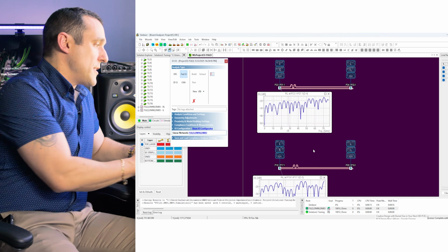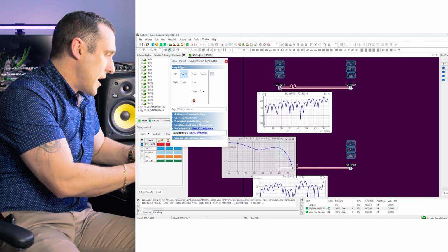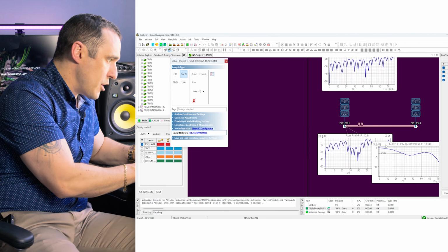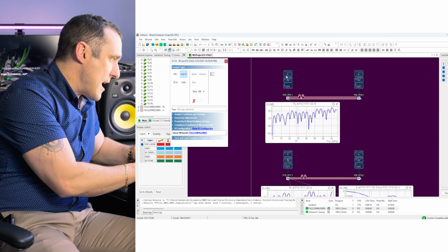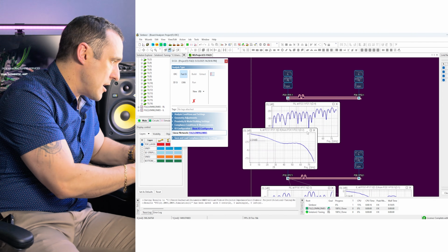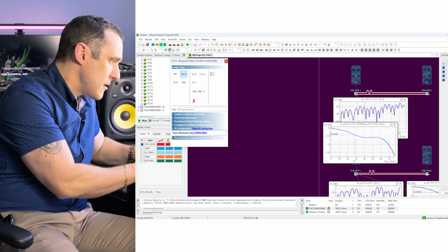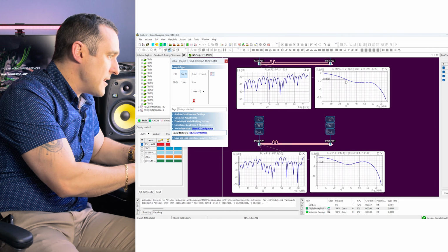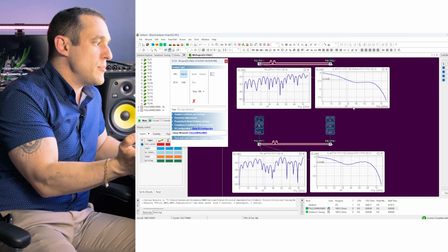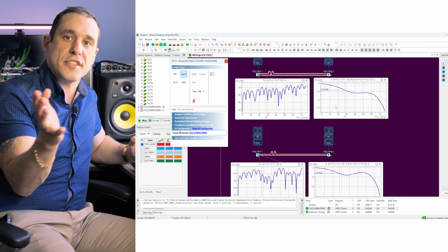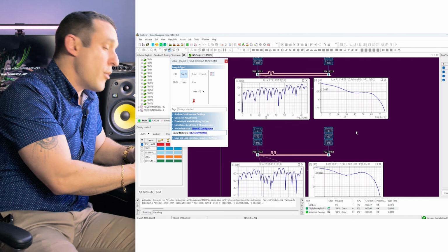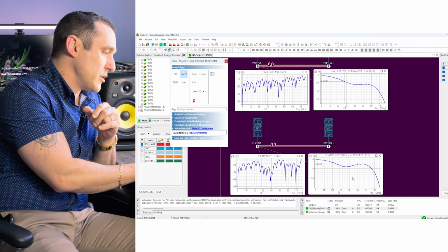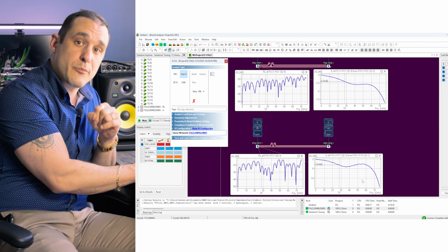Let's also look at the insertion loss for these two interconnects. So if I bring up the insertion loss and I pin it, and we'll go ahead and move this down over here, and same thing up here. I bring up the insertion loss and I pin it. You can see here that at about 28 gigahertz, we have negative 2 dB of insertion loss in the traces that are spaced 10 mil apart. But when we have the traces spaced closer together, you can see here we get an additional dB of insertion loss at the same frequency.